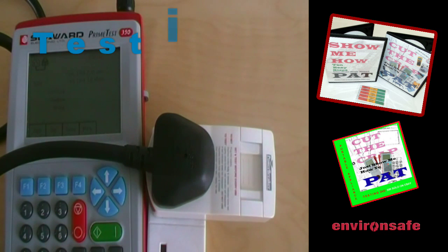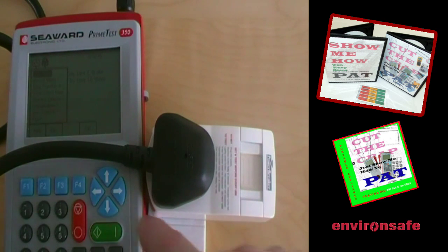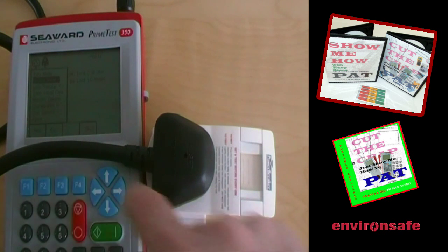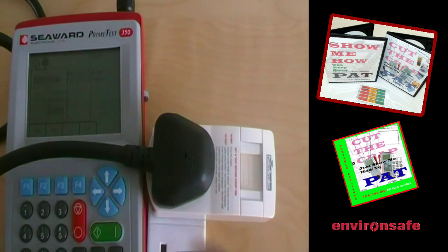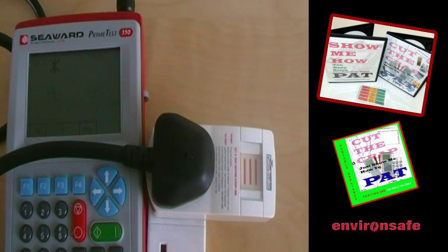How to conduct an RCD test. Excuse the way I've got it set up, but I needed to get it all into the video. Press F4 for menu. Scroll down for manual mode, F4 to select, and scroll down for the RCD check, and F4 to OK that. We need to set the RCD.